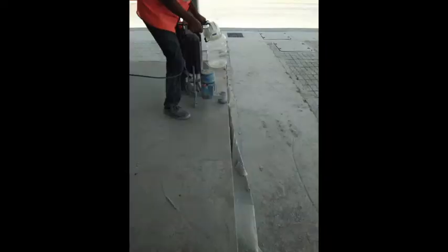So if you are looking at a polished concrete floor, you should be aware that this is a limitation. If you're looking at a polished concrete floor in a space where aesthetics are very important, then you have to design your floor accordingly. Maybe have a gap from the edges which can be fit in with another tile or something like that. So these three aspects of the initial grind are crucial, and ensuring that any contractor, any provider actually follows these initial grind processes is important for a well-performing floor.